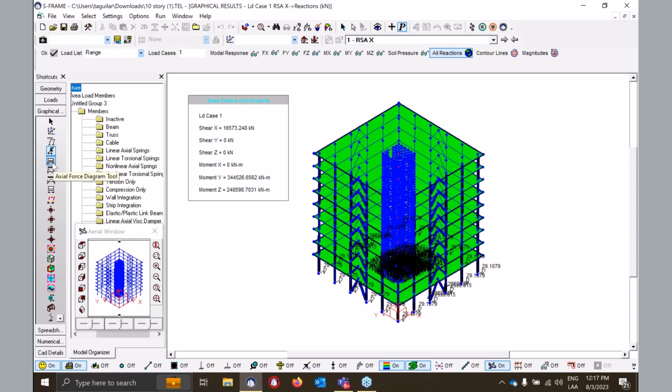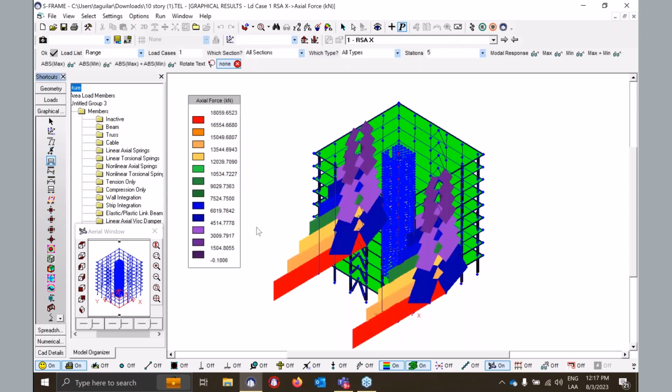Next, I want to showcase the action force diagrams that we have here. And please note that these are all in tension due to the fact that the RSA model combination method squares our model results into a usable set, losing the sign. As Matt mentioned, there are some ways around this, but this is a byproduct of the RSA method.